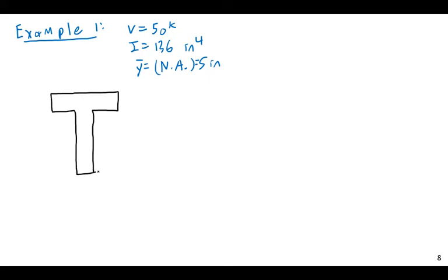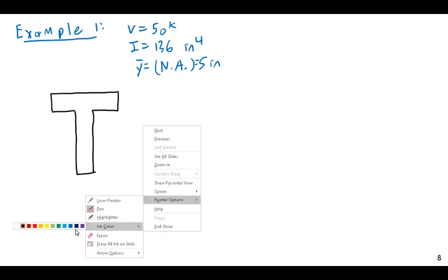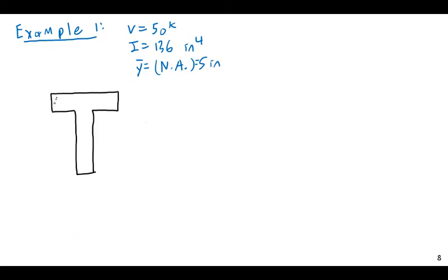So we're going to have a cross-section here, a T-shape. So we now have a non-symmetric shape. It is horizontally symmetric, but it is not vertically symmetric. We have a point B here. And then the upper flange is 2 inches. The way we describe this, we use the same terminology as we do a W section, flange and web. There's not a T section, you can essentially think of it as a W section with only one web, with only one flange.